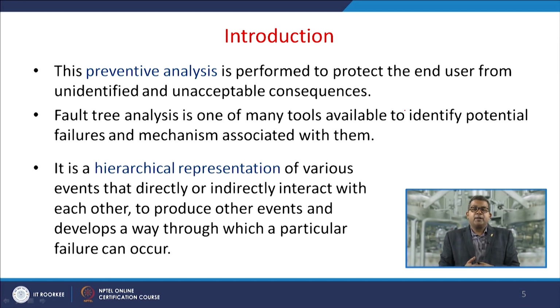Now, this is usually a preventive analysis, and it is performed to protect the end user from unidentified and unacceptable consequences. So, fault tree analysis is one of many tools available to identify potential failures and the mechanisms associated with them. It is a hierarchical representation of various events that directly or indirectly interact with each other. So, you have different events in a particular plant, and they may be either interactive or non-interactive with each other.